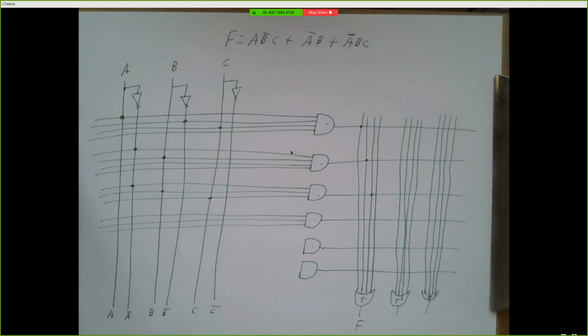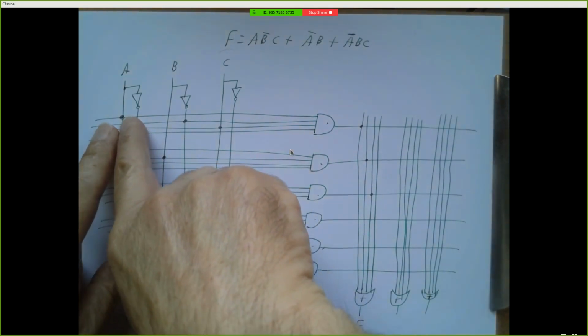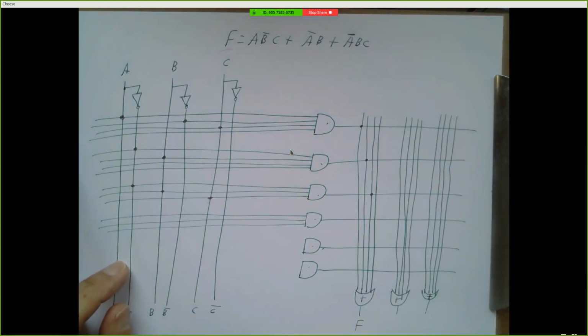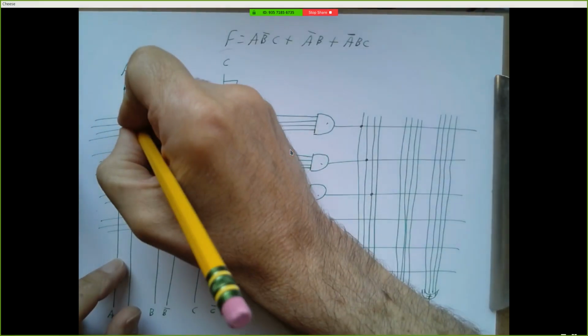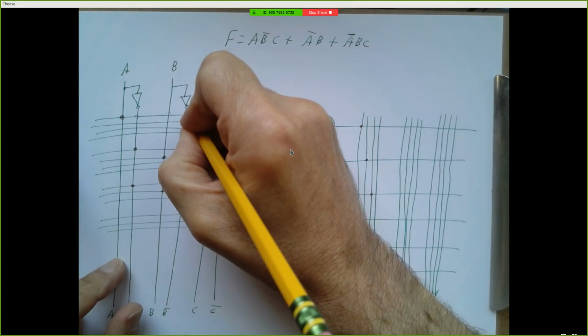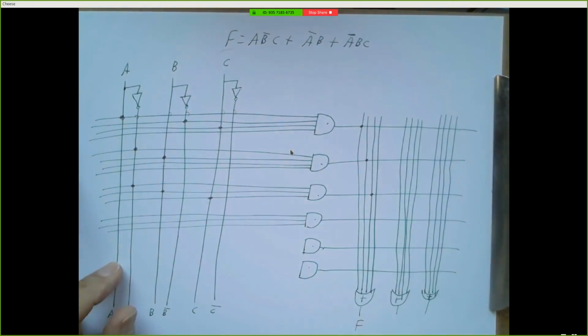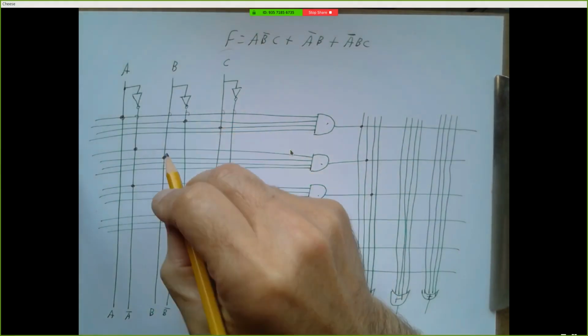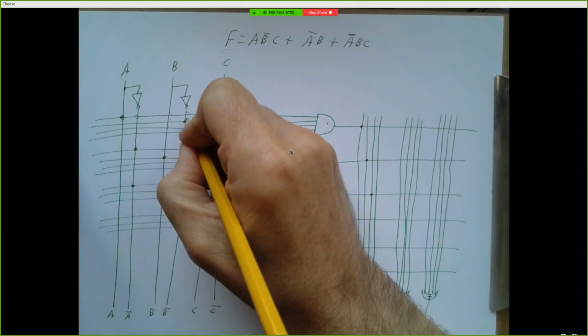So imagine if we had a fuse connecting every horizontal line with every vertical line. Okay, just a little piece of metal that connected these together. And then from outside, if there was a way to come in and push a bunch of current through the fuses that you wanted to get rid of. So we'd start off with fuses everywhere.